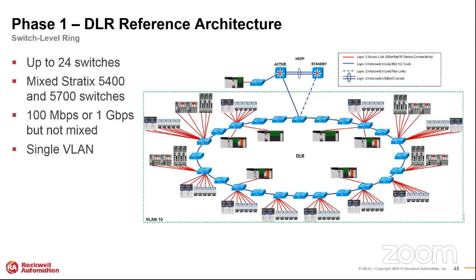All of the devices in the ring itself are L8 controllers or even redundant L7 ControlLogix systems. They have some GuardLogix in there, as well as drives and remote I/O devices like Point I/O. And everything as of the latest phase 3 has been tested with the latest firmware, up to version 32 in the ControlLogix controllers.